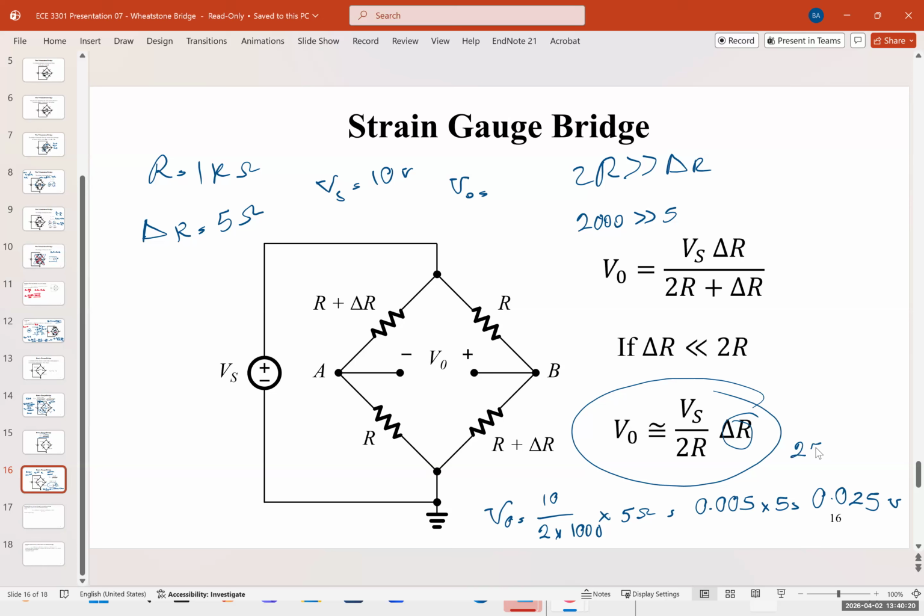In other words, it's 25 millivolts. And usually the voltages are around this. Now, usually the factory gives us a data sheet and says each 5 millivolts is equivalent to, if you want to measure air pressure, something like 1 bar or 10 psi, or 1 psi, for example. So if you have 1 millivolt, it's going to be 1/5 of that. And